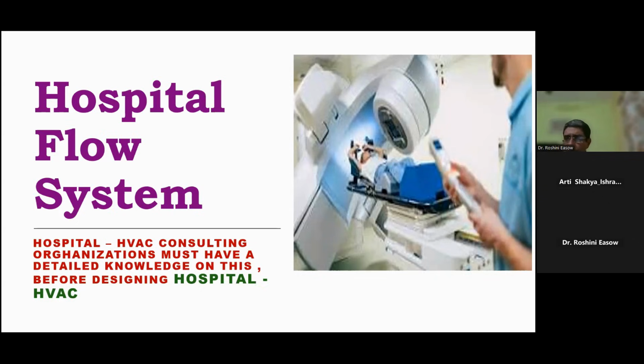Now, when I try to bring some HVAC people to a hospital, they find it uncomfortable because they are not aware of the hospital flow system, how a hospital works. Same thing if you think about the pharmaceutical industry: if a consultant does not know how pharma manufacturing works, there are different types of pharma products like tablets, liquids, gels. The consultant should know how the manufacturing process is done. Like the very typical thing in tablet manufacturing, the granulation. How granulation and HVAC design are interlinked.